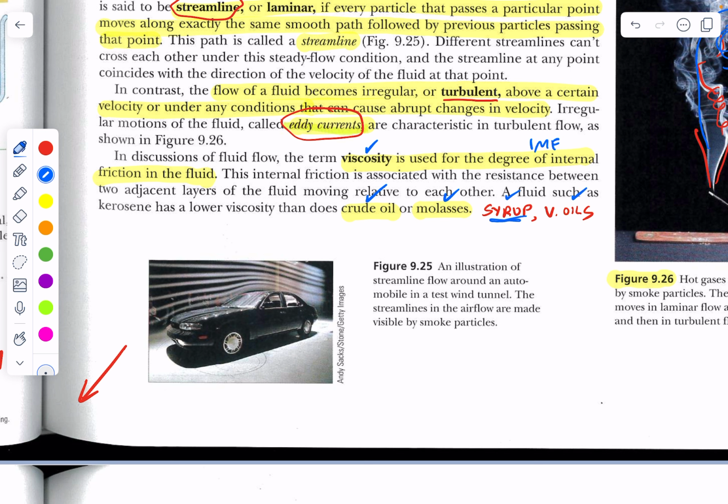In your car, you might use 10W40 motor oil, or 10W30 or some other motor oil. We want the thicker oils down south where it's hot, and increased temperature causes the oil to get runnier. And up north, you want a thinner oil. That thinner oil is necessary because it's cold for much of the year, and you don't want the oil to become so thick and viscous that it's having trouble lubricating the place where the piston moves in and out of